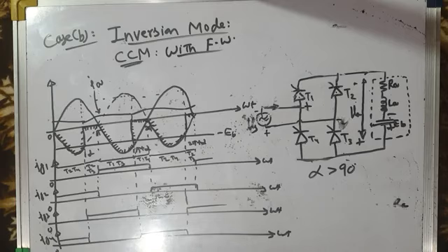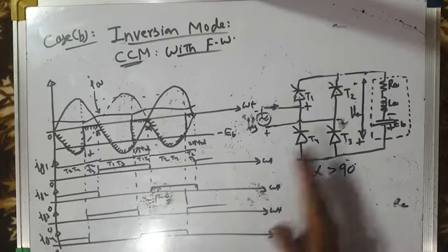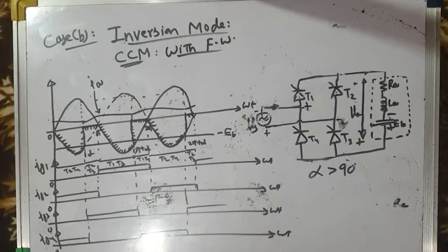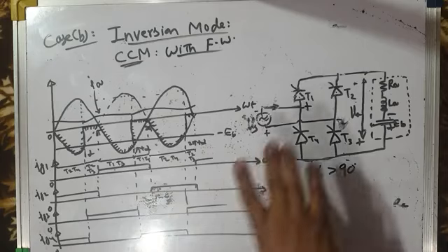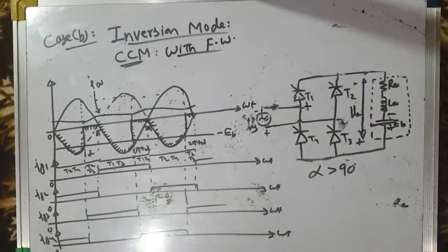So therefore, with controlled freewheeling, for a single phase full converter feeding a separately excited DC motor drive, we can achieve two objectives: whether the drive is operating in rectification mode or in inversion mode of operation, the average load voltage increases, and secondly, the supply side or the source power factor improves.